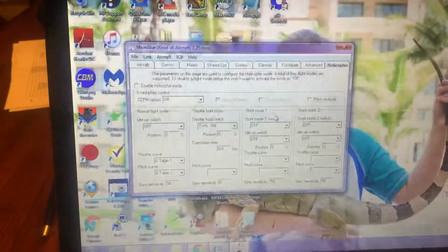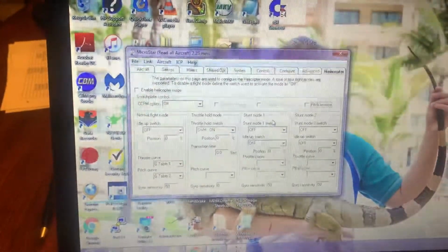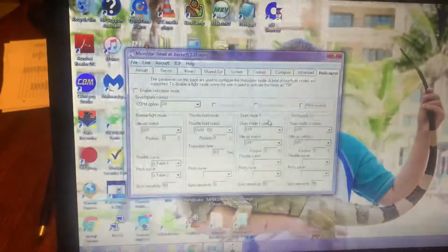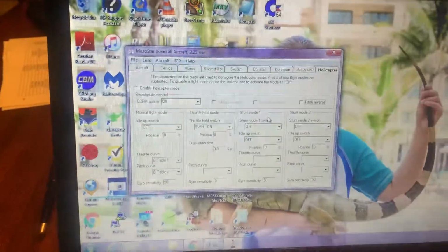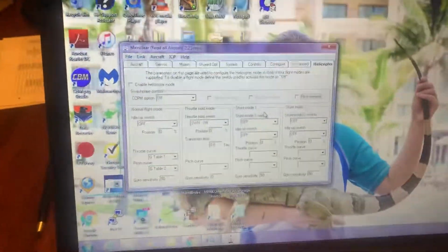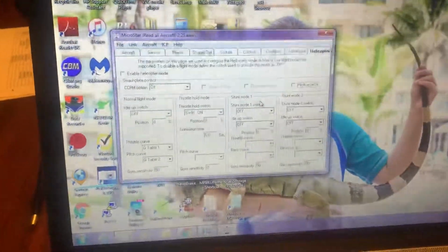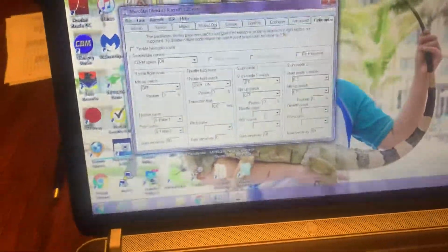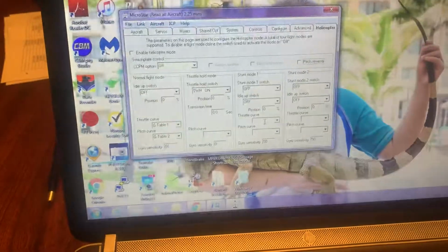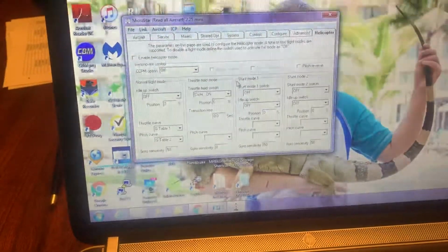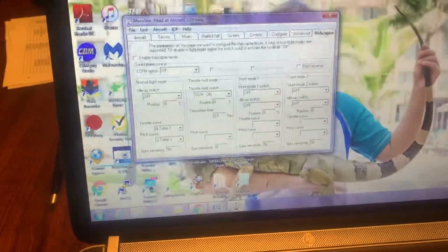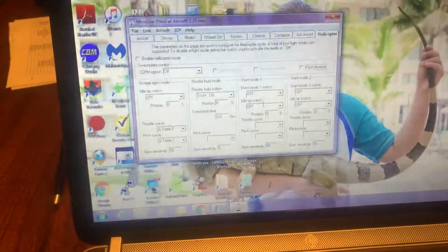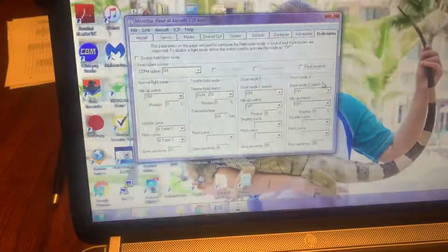These would be where you'd have set your collective stick and throttle stick, where your pitch curve would have center stick at 0 degrees, and then high stick would be positive, let's say 10, maybe even 12 degrees. And then low stick would be negative 10 or 12 degrees. And you can run an independent throttle curve to where you've got high throttle at the parts of the curve where you have the most pitch. And then the area where you have the least pitch, you could bring your throttle value down some. Again, you got 2 different stunt modes where you could do that.